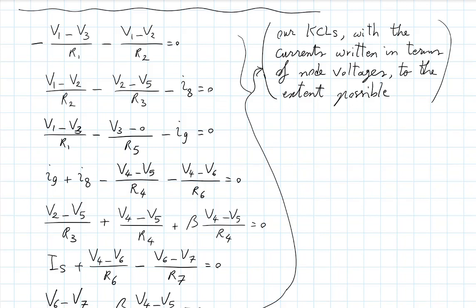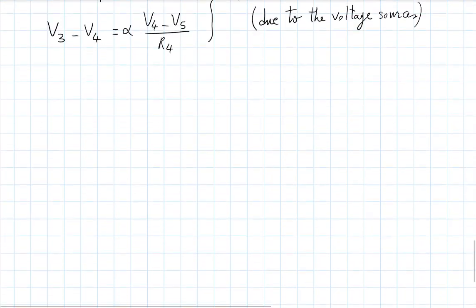So here I have V1 by 1 over R1 and 1 over R2, both with negative sign. So let's take everything and multiply by -1 to get rid of that minus sign, okay? So then I'd have 1 over R1 plus 1 over R2 multiplying V1, and then I would have minus 1 over R2 multiplying V2, and I'd have minus 1 over R1 multiplying V3. So now basically simplifying the equations.